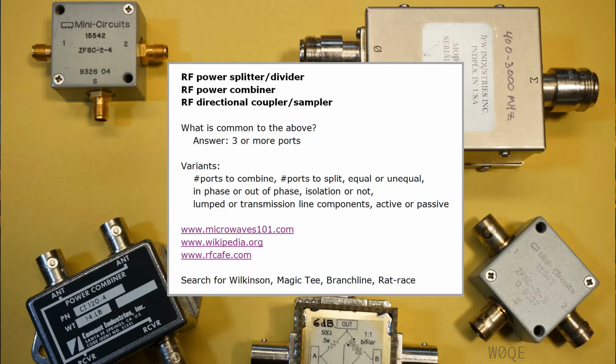In phase or out of phase. The topology of some power combiners is such that the inputs are expected to be in phase, and in others the inputs are expected to be out of phase. Some circuits can be operated as either, based on which ports you treat as inputs and which ports you treat as outputs. It's all dependent on the hardware involved in the combiner.